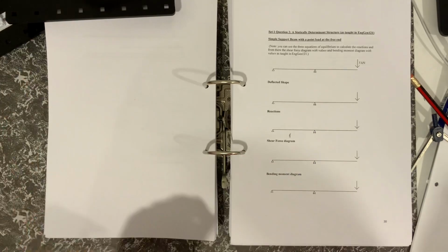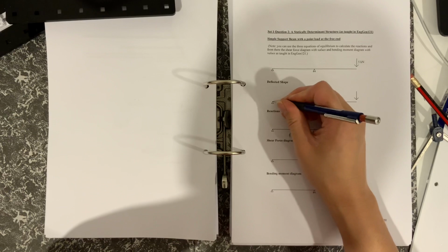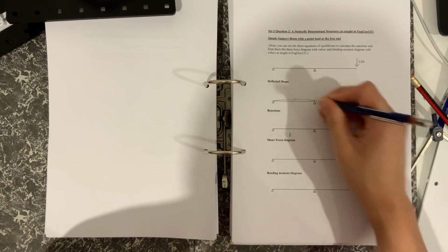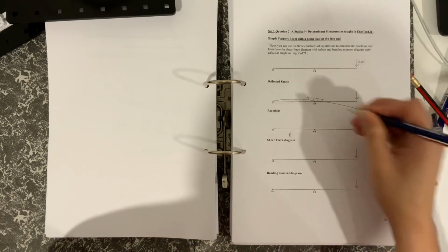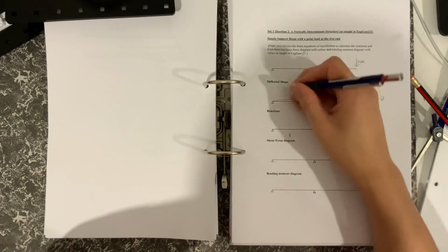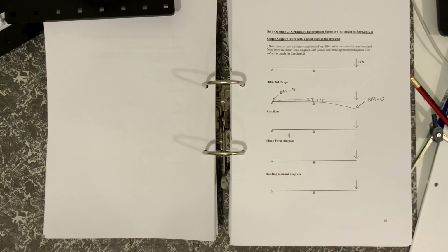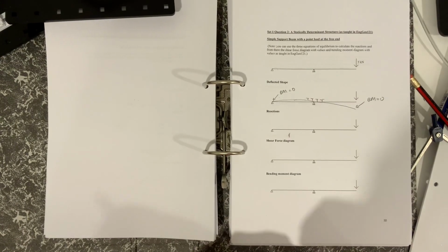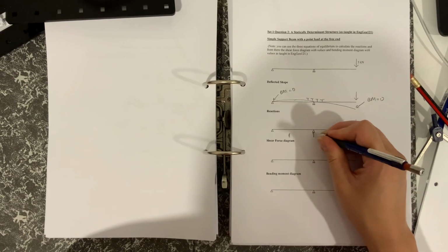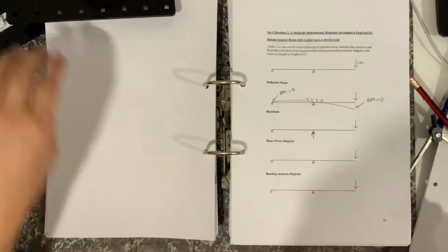So let's try and sketch that. So deflected shape. I'll just draw it here. And then just show that as being the tension side. And then here I could say bending moment equals 0 or curvature equals 0, since bending moment is proportional to curvature. Bending moment is equal to 0 at that point there. So the reaction, so that's coming down, so we would show a reaction there, which would be going upwards.